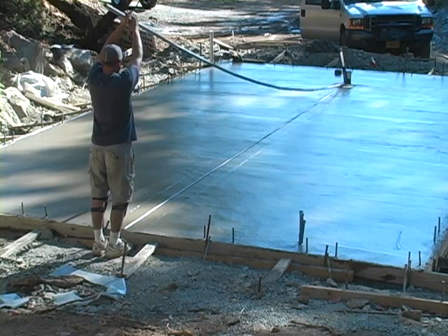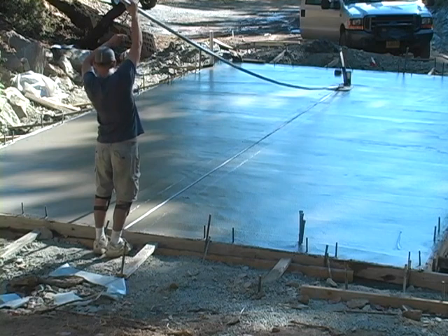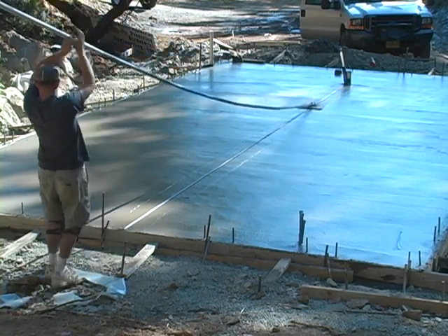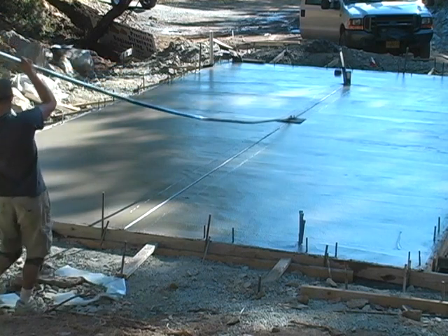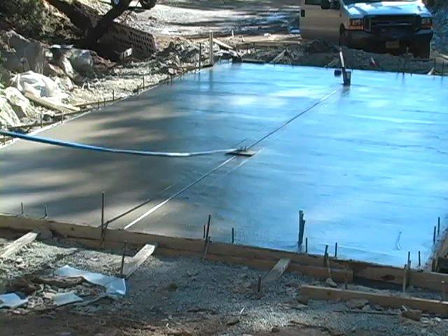And then here the difficult part is lifting it high enough so that the back end comes off of the concrete before you start to draw it towards you. If you don't lift the back end off the concrete as you draw towards yourself, it'll actually rip the concrete out and make a total mess of the concrete.